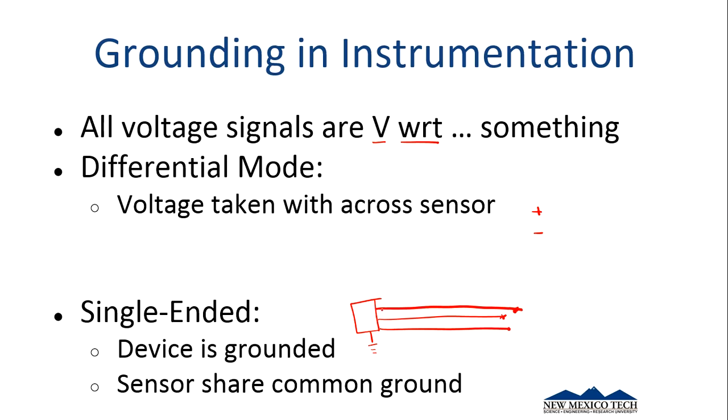We're still measuring a voltage across something. We're just saying V1 with respect to ground, V2 with respect to ground, V3 with respect to ground. So we need to make sure when we do this that all these are using the same ground, that's that actual assumption that we can make, and that actually checks out. Otherwise, we really need to go to differential mode to make sure that we're actually measuring the voltage drop across what we think we're measuring the voltage drop.